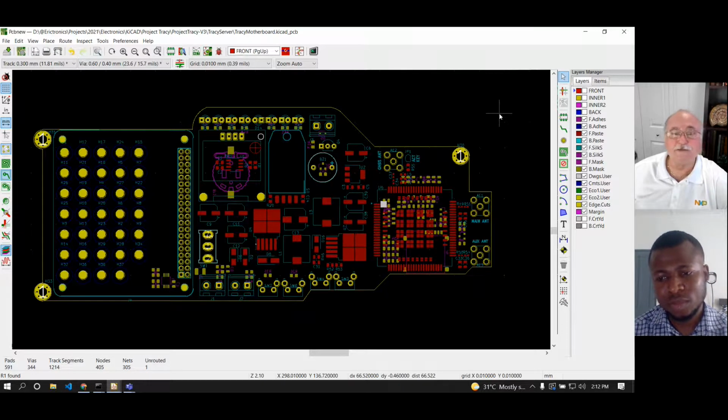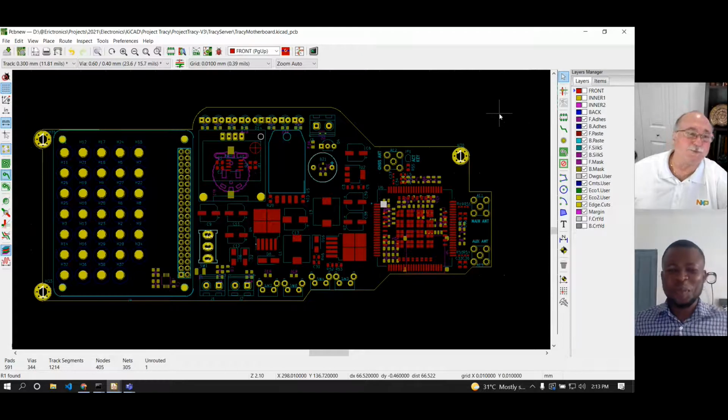And in this case, because you've been able to create good transmission lines on all the signal layers, 1, 3, and 4, by your proper use of ground plane and ground flood, it's as good as it can be.